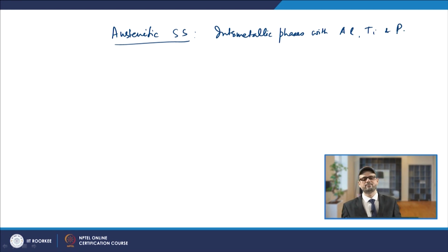These steels have good corrosion resistance compared to other stainless steels. They normally become brittle when they are exposed for many hours at somewhat elevated temperature, maybe close to 300 degrees centigrade. So normally we limit their use to the lower temperature range, and try to keep the working temperature somewhat smaller in those cases.